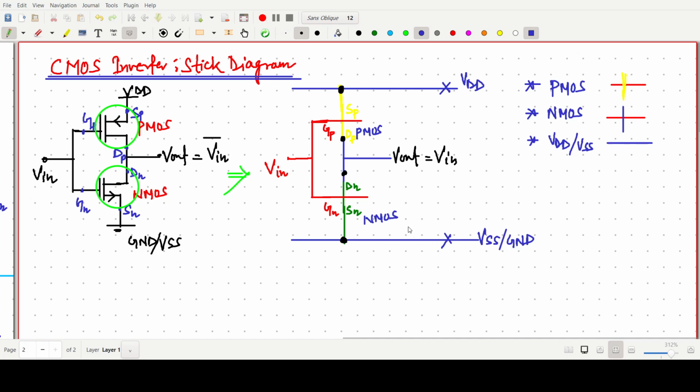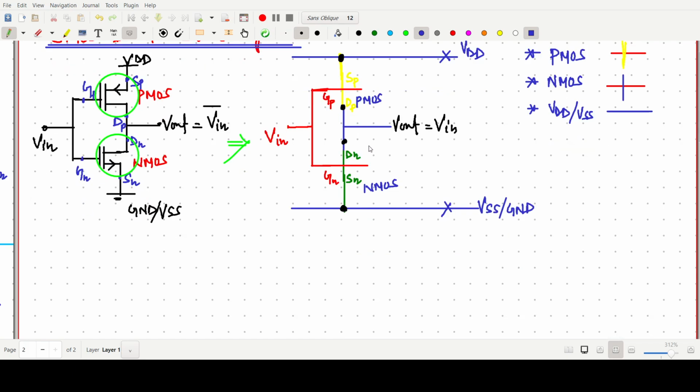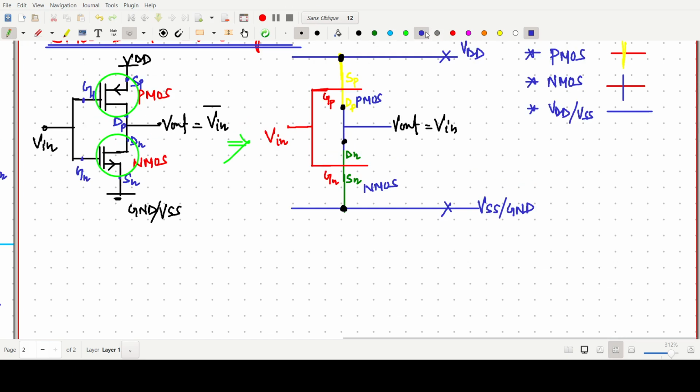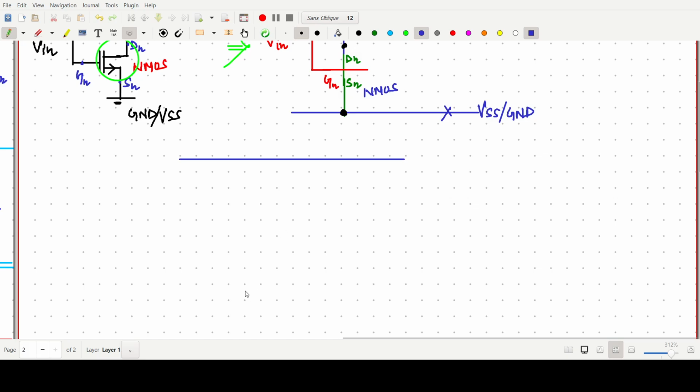Okay, so now in this case there are so many red colors used, the polysilicon. In layout information it is observed that the polysilicon will be very less. Below 14% we have to use the polysilicon. So another way to draw, the same thing we can do like this. Very first we use a metal line. For example, we are just making the metal lines like VDD and VSS.